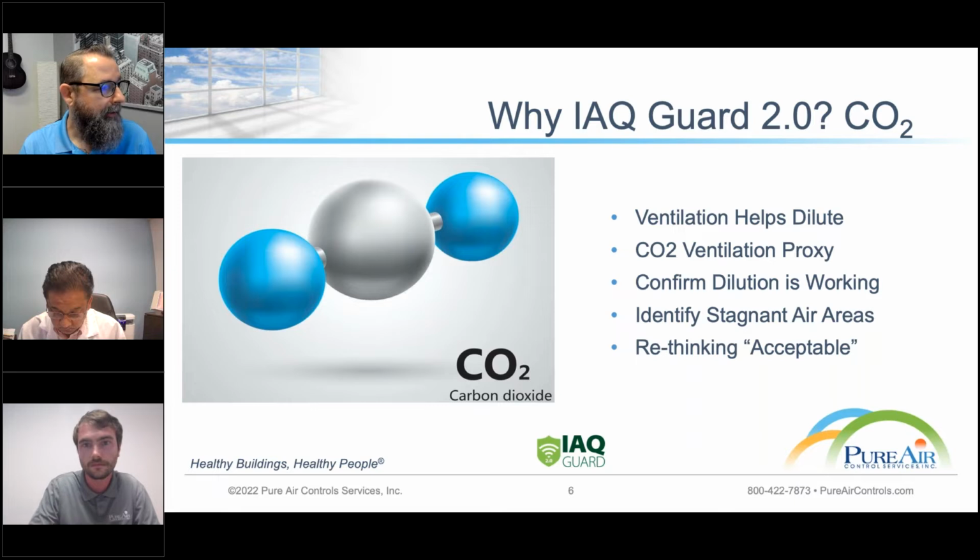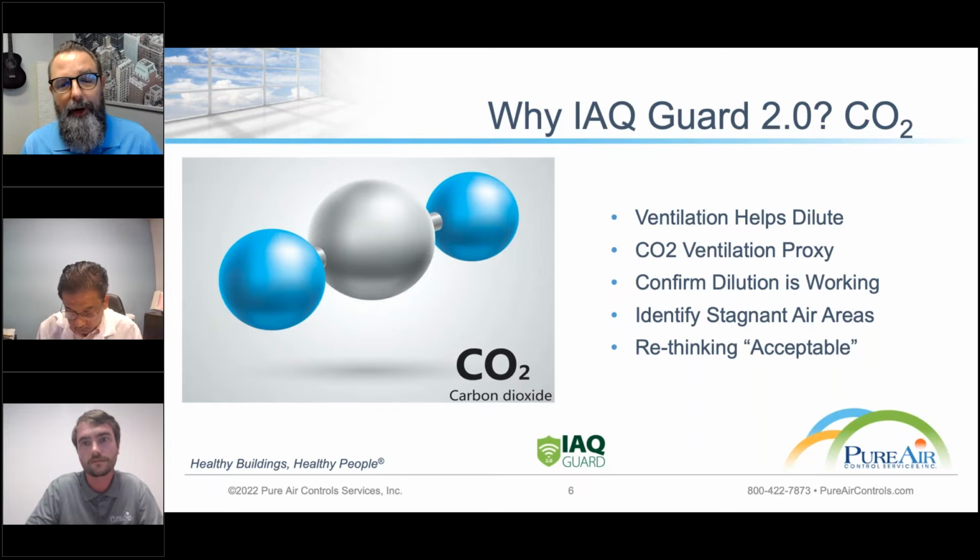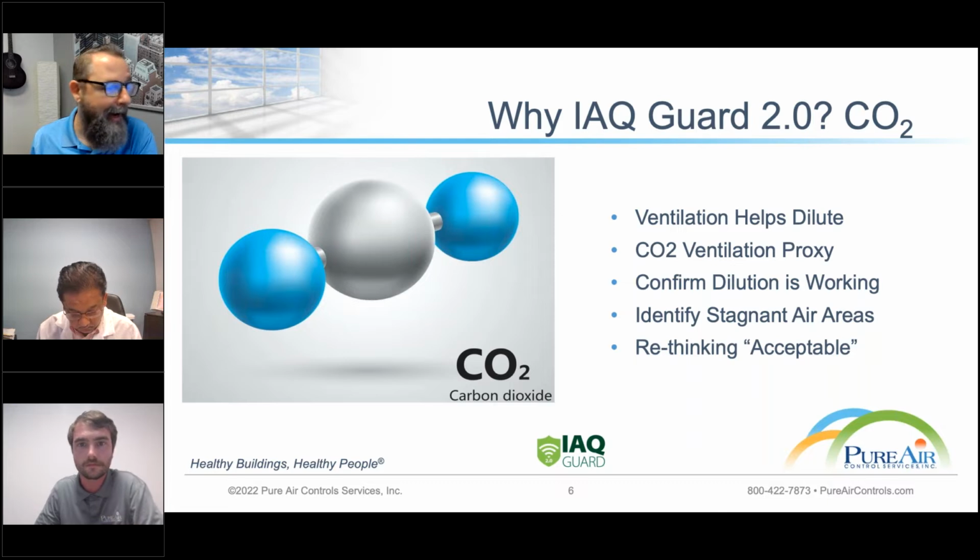And so ventilation helps dilute the buildup of CO2 within a building. And then there's some controversy to this, and I think both of my guests today understand this from a building sciences perspective, but CO2 might be considered a proxy for ventilation in some circumstances. Not always, but because you can't see it, if you can measure it through an IAQ monitoring platform, you can see when a space is occupied by people, because you'll see the trend go up for CO2, and then you can see when a building's not occupied.